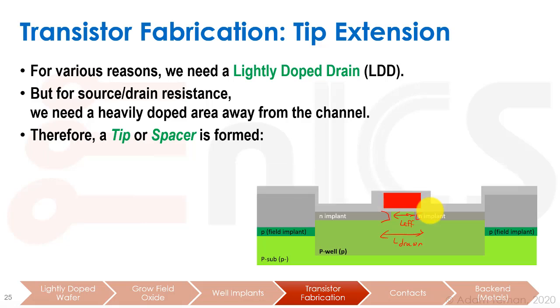Okay. Then we're going to build up an oxide layer on top of everything. As you see, something interesting in the oxide layer, here it's flat, but here we have this gate, and the gate's pretty high actually. So what happens is when we deposit this oxide, it actually is pretty thick over here, much thicker than over here.